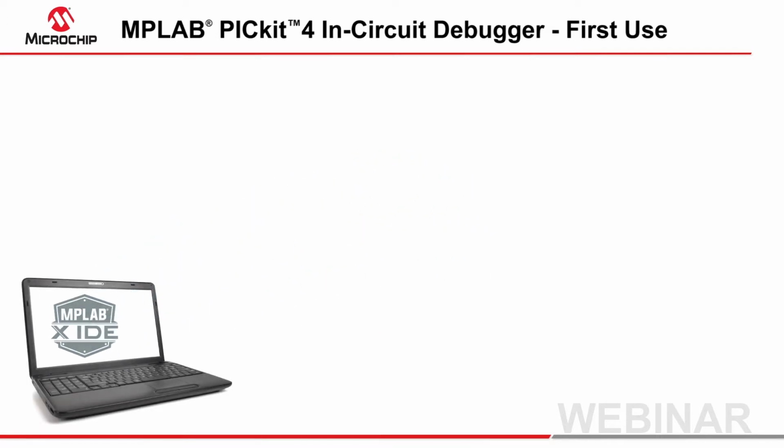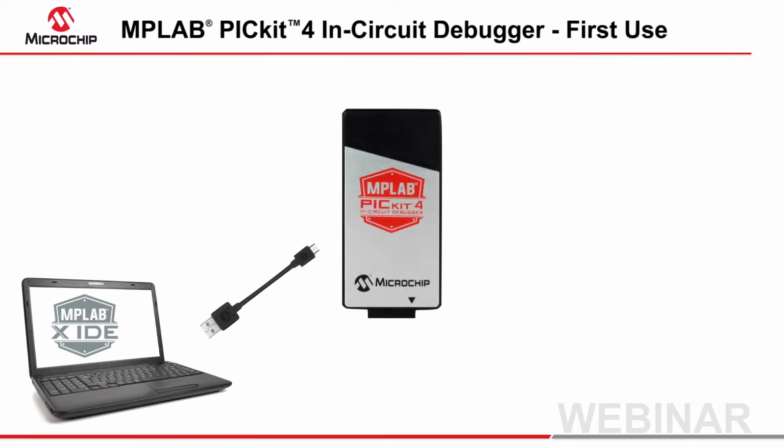Now connect a USB cable from your host PC to the PICkit 4. This allows communication between the debugger and the IDE. After connection, the status light should illuminate, indicating that power is available via the USB, and it should turn blue to show that the communication link is active.